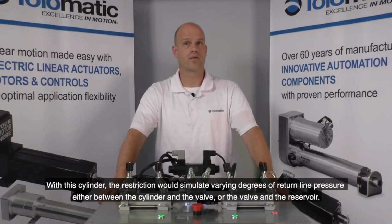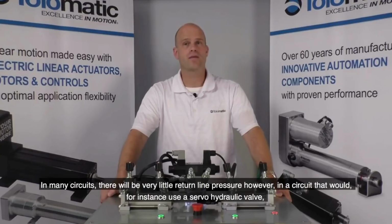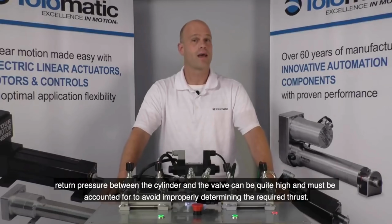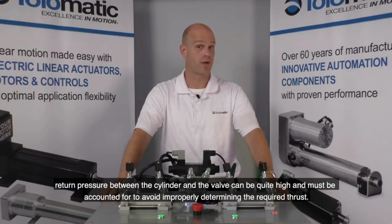With this cylinder, the restriction would simulate varying degrees of return line pressure either between the cylinder and the valve, or the valve and the reservoir. In many circuits, there will be very little return line pressure. However, in a circuit that would, for instance, use a servo hydraulic valve, return pressures between the cylinder and that valve can be quite high and must be accounted for to avoid improperly determining the required thrust.